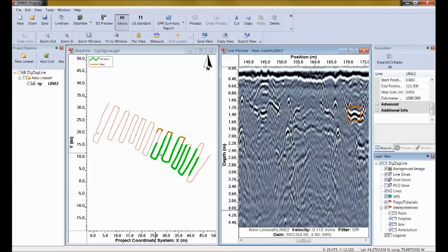Here's the horizon. The green line is the horizon I put in, and the brown or orangey color are the boxes that I put in. So now I notice that, oh wait a minute, the odd feature that I drew those boxes around seems to be associated with the point where the GPR turned around and was coming back in the other direction. So the boxes help me to quickly interpret the U-shaped features as a layer distorted when the GPR turns around while zigzagging.